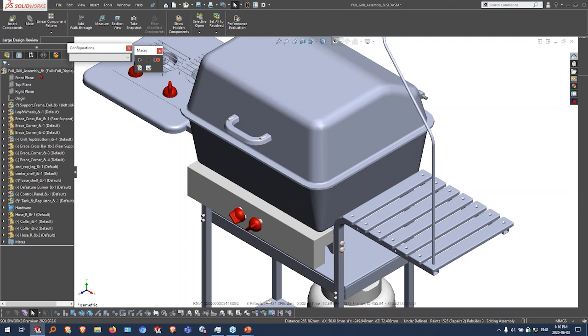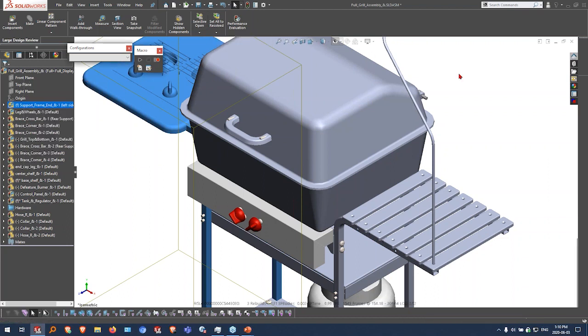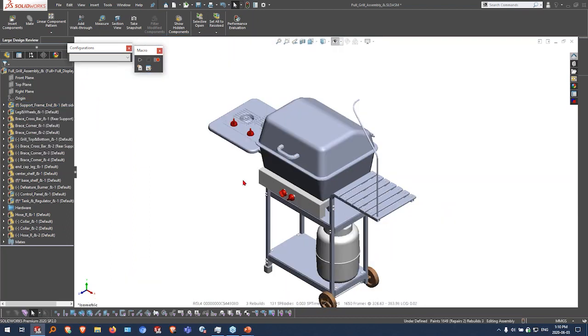Then when you're ready to, I know a lot of our customers will look at this and say, okay, that's great, but I have to also work with my sketches and resolve components. Then we can look at either resolving selected components, or let's assume, for example, you made a whole bunch of updates either in your top level or your subassembly. Now we can say, for example, in here, set all to resolved.